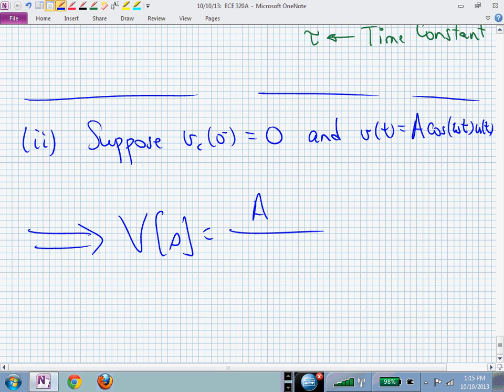In 320, we're going to damp those out. We're going to allow those to be exponentially damped so you can be done. We're going to have mixing of transients and sinusoidal behavior together. So we can now be finished instead of just sitting there like this. But now what are we doing? Please answer. We're just shaking, aren't we? With a frequency of omega. What's the denominator when we shake at omega? S squared plus omega squared.